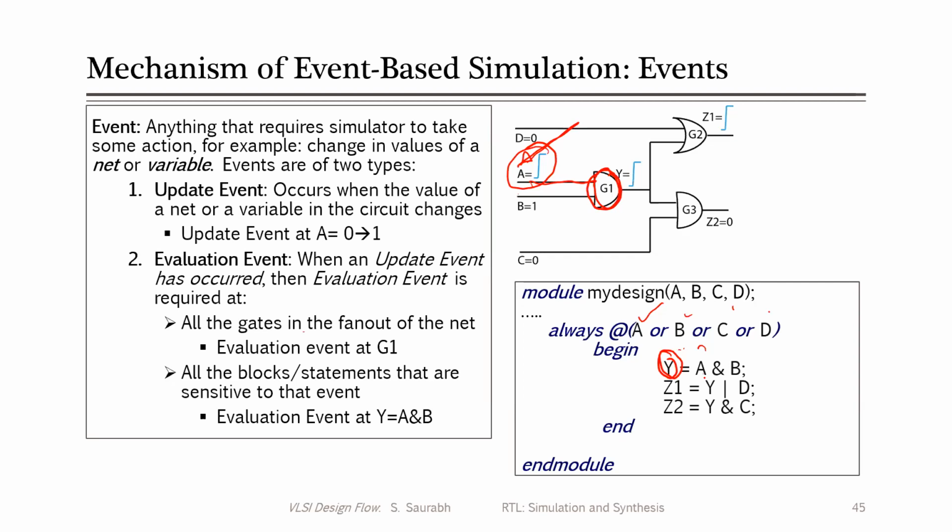For example, you are expecting something to be in the output from an RTL code or test bench, but it is not producing that output. Now, how to debug? To debug that, you should understand what the simulator did. How did it compute? Otherwise, you'll never be able to debug your design, your test benches, and other things. To debug those things, you should understand what the simulator will do.